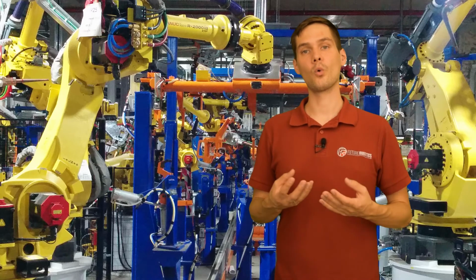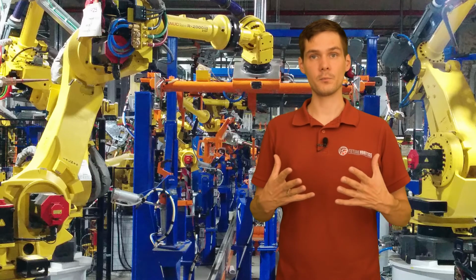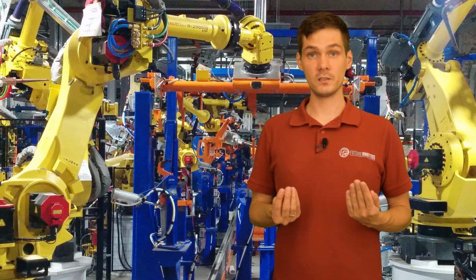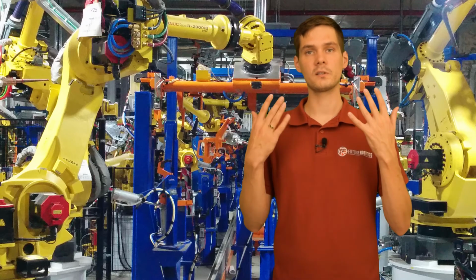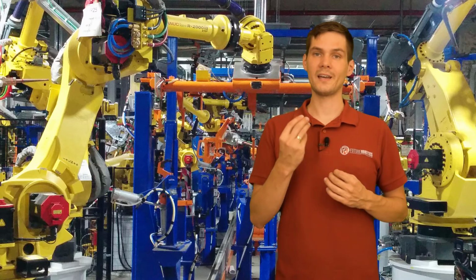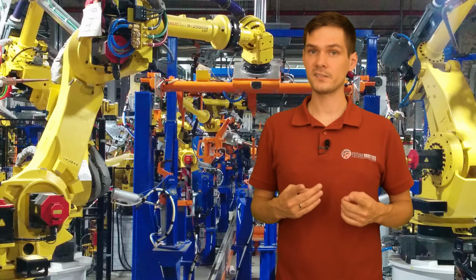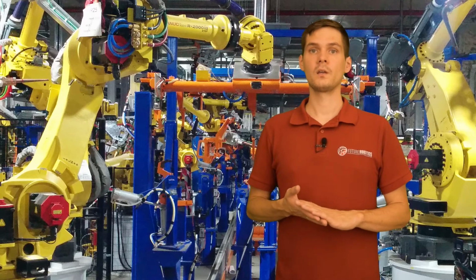The robot needs to know where it's working at. You have your world frame, which is your base frame, which is where the robot is at. And that's the world frame. So that's user frame 0. But you want to use user frames to navigate through the points and to just know where the robot is at. And at the exercises I will explain to you why, and you can do cool things with it.